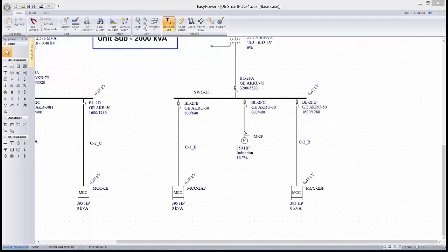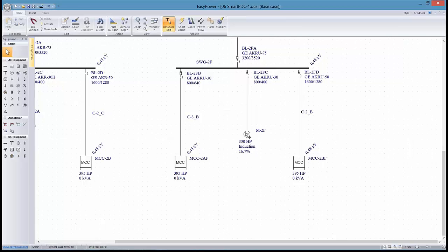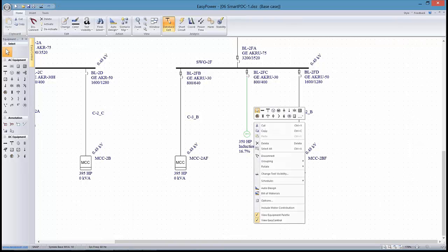And so the question is, does this breaker actually, as we're doing coordination, it obviously doesn't do anything to protect the incident energy on this bus. What does it do, and what kind of protection does it do if we're considering incident energy actually on the motor itself?